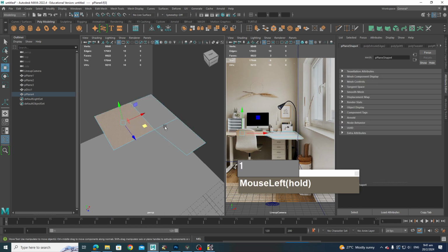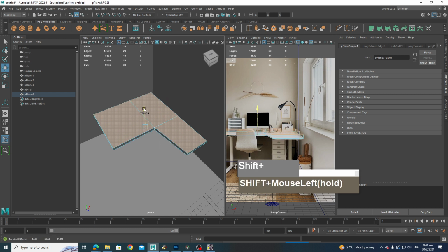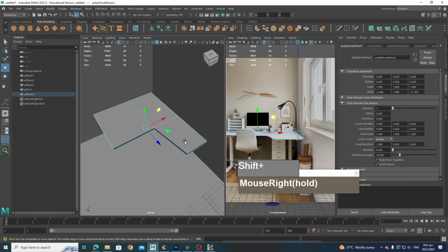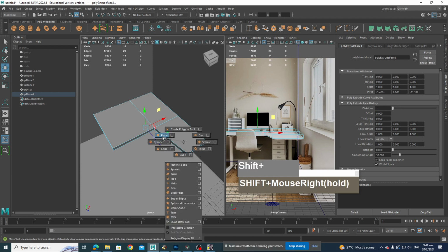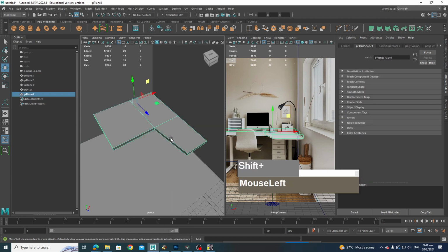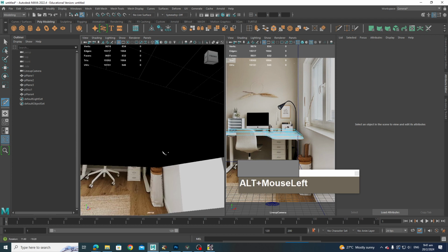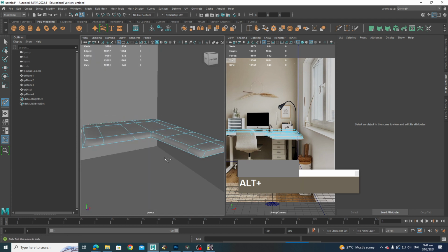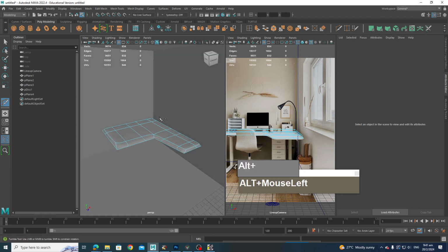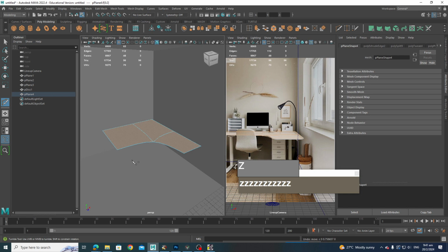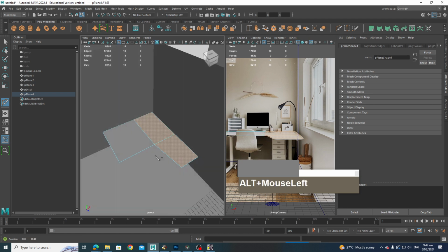What I see is that the plane is extruded, and after that a lot of students just simply add a bunch of edge loops. So I'll show you the wrong example. You extrude or insert a bunch of supporting edge loops like that, and then press 3 and just hope for the best. And then you can see this one is not working. I got an inverted face at the bottom. So I'll show you the correct way. Let me just undo that and go back to level 1 again.